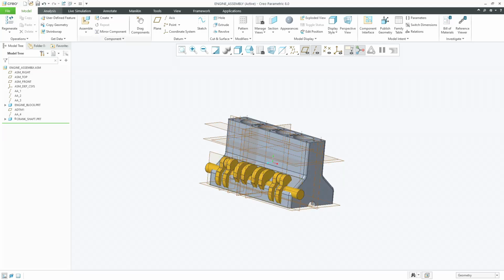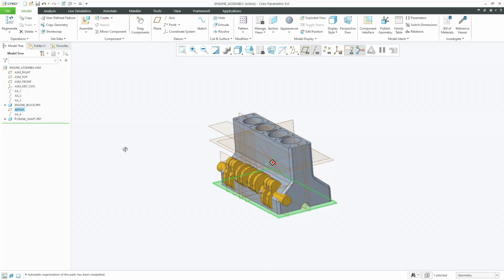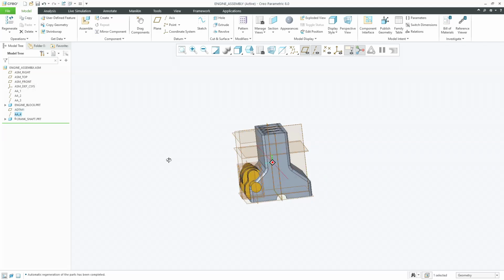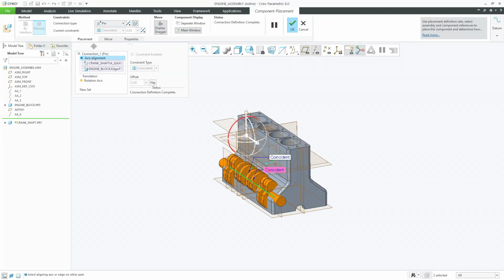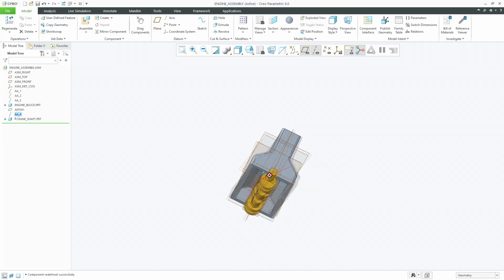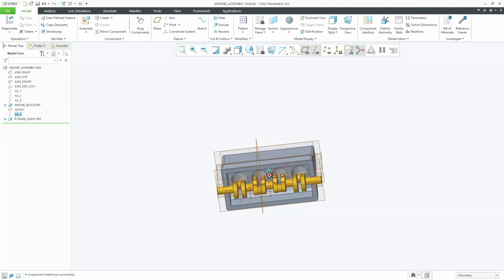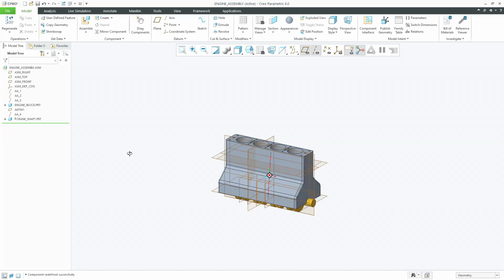In this, I would like to make a small modification on the plane which we have created. So the axis line is here. I would like to regenerate or modify this since there is a slight mistake in it. So I'm selecting this, remodifying this axis, and just clicking OK. Now you can see the crankshaft has been assembled to its position with reference to axis orientation and translation motion to arrest this. Now this crankshaft has 1 degree of freedom, where it is going to rotate.